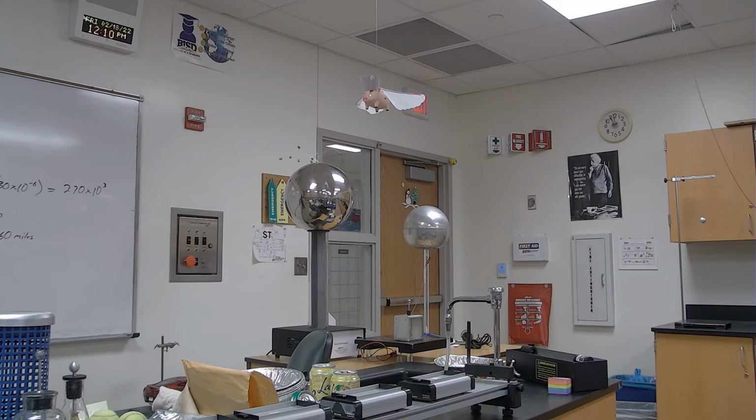So just for comparison, if you want a 1 farad capacitor, and I have some of those too, they're actually smaller than that. A 1 farad capacitor made out of a sphere would have to be almost 6 million miles in circumference. No, in radius. Yeah, that's radius. So that's much, much larger than the Earth. And I have 1 farad capacitors that are smaller than this. Hence, parallel plate capacitors is where it's at when you're talking about capacitors. They don't make spherical capacitors to actually do anything, right?